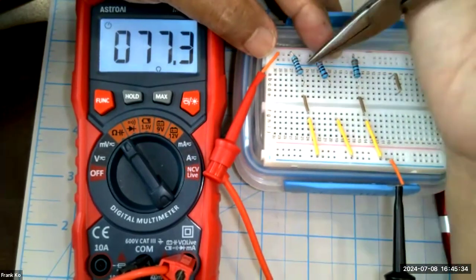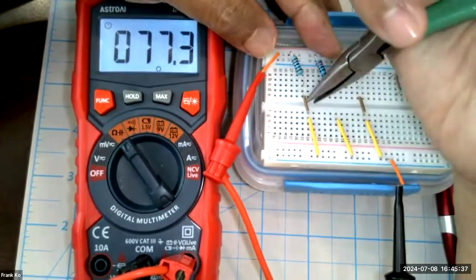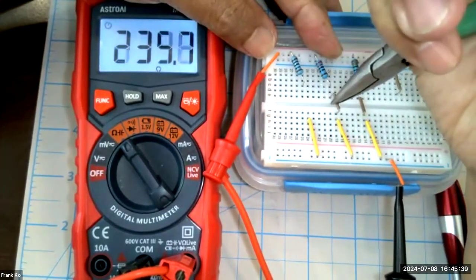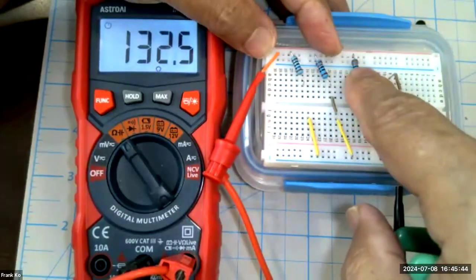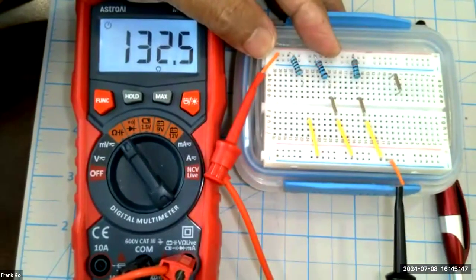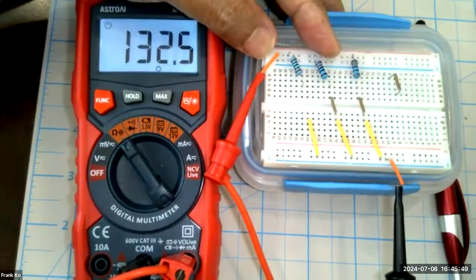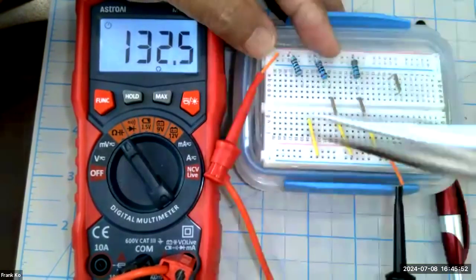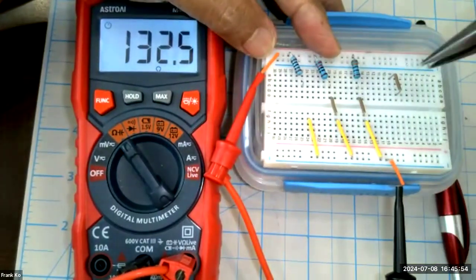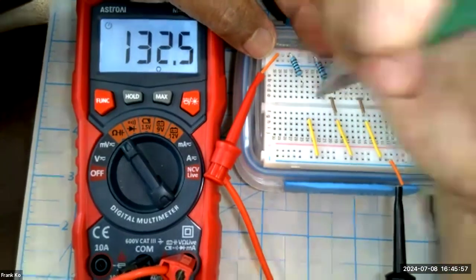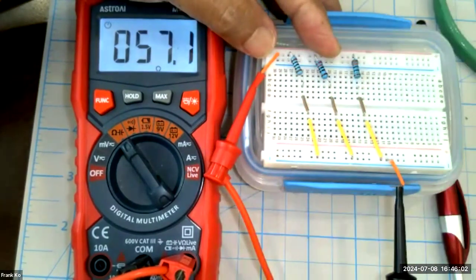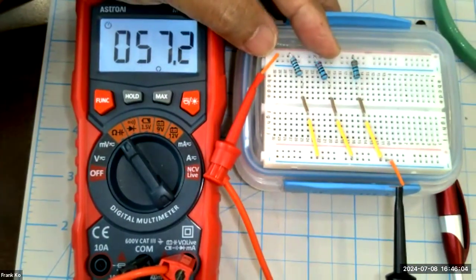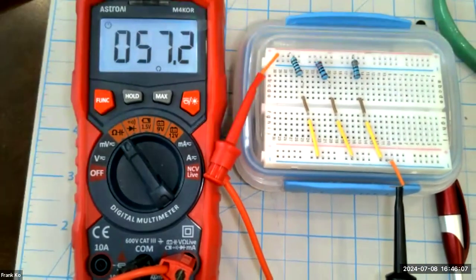And the last consideration is maybe something was wrong with the first resistor path. So we yank this guy out, put this over here. And very quickly, we were able to determine R2 parallel with R3, with R1 being faulted out for whatever reason. In this case, I've removed it from the circuit by virtue of removing the jumper. We measure 132, which jives with our calculated value. Hot stuff. Hopefully, you've just done this. Put this back, and do we achieve our original 57.2 ohms? We do indeed.